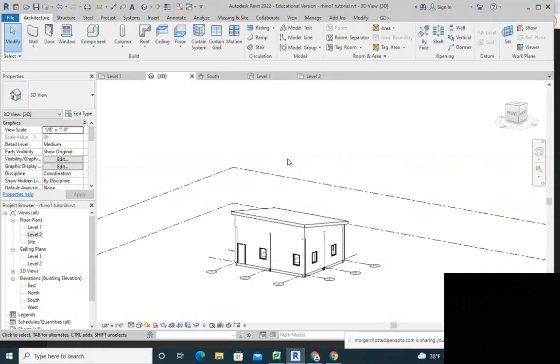Done. Okay, so you need to add one more line here. So you can use that line tool. Add a line from there to there. Then offset it. So click the offset button. Second one. Yep. And then click on each side.